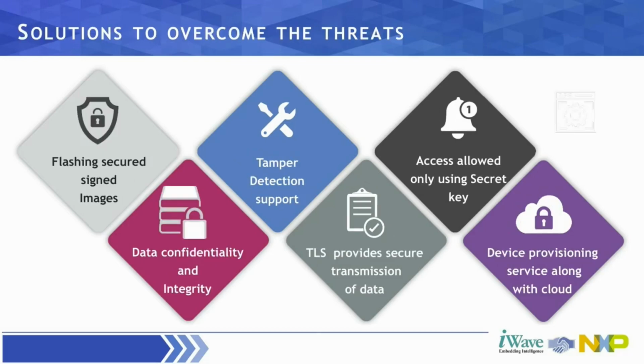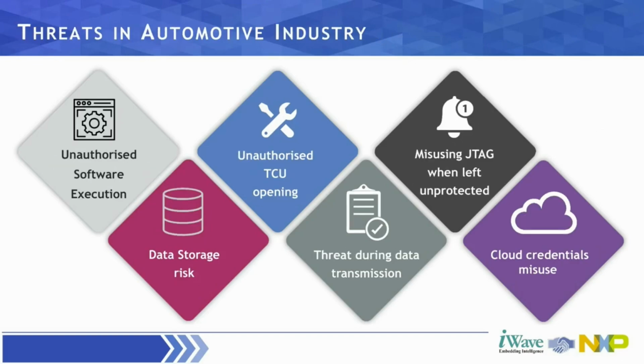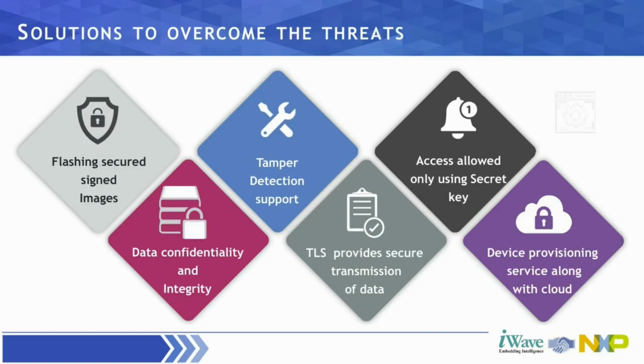Flashing using secured signed images makes sure that unauthorized software execution does not take place. Be it the ECUs or the different types of gateways, the complete firmware is signed to make sure that the right firmware is executed on your different gateways. Data confidentiality and integrity using the different signing mechanisms, your encryption mechanism, and the complete key generation and management. This is what needs to be taken care of from your data confidentiality perspective.